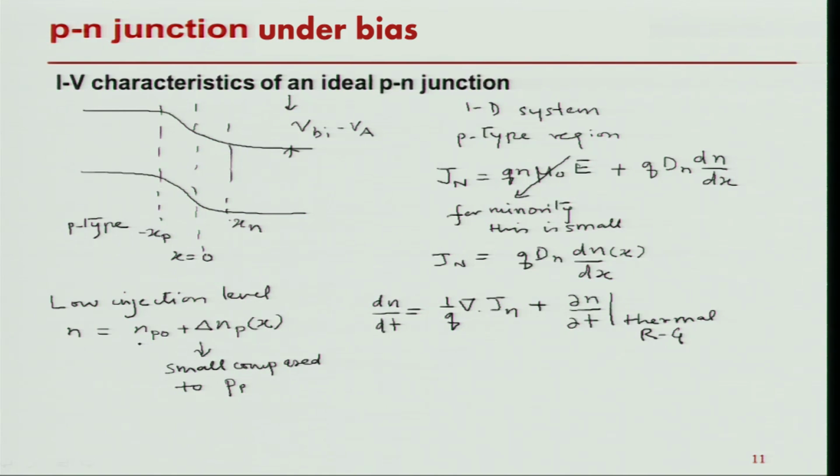Now, I know on the p side that there is no change in the concentration, it is uniformly doped, and in trying to find a steady state solution, there will be no change in time also.